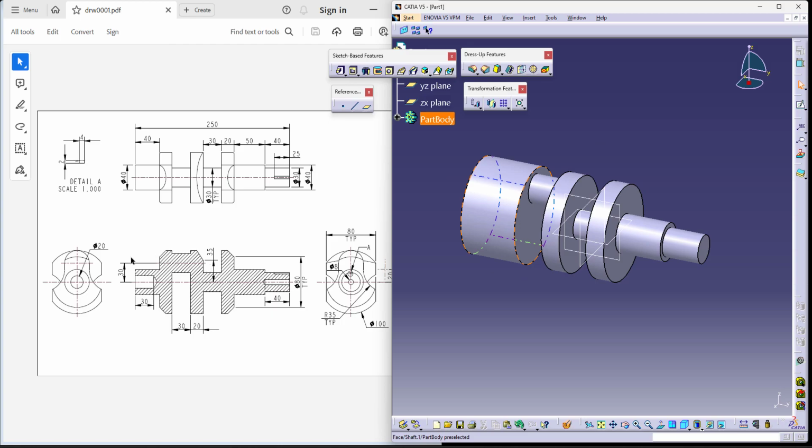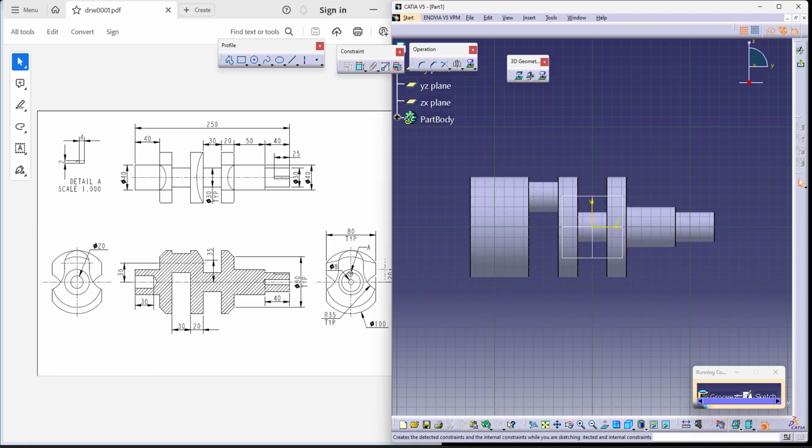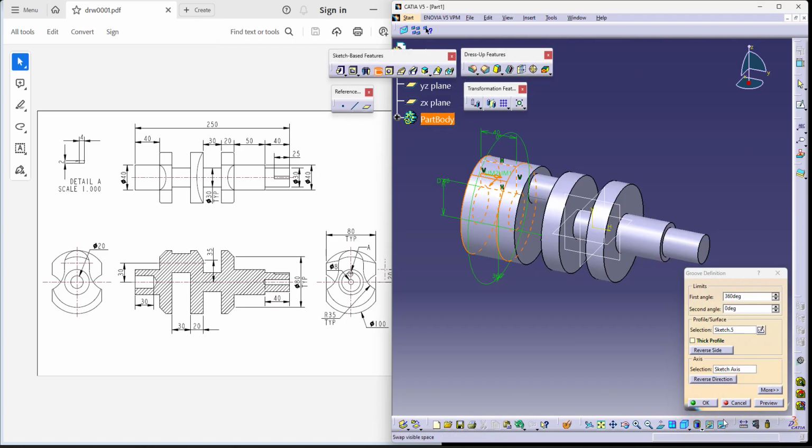Now there's also another cut, 40 by 40. So again, let's try to use the same groove command. This is a very easy cut which we have already done before. But again, let me try to take the references as well as the axes. And I want this reference as well. Now, let me go back to making my profile of which I want to remove and then start dimensioning it. This is supposed to be 40, which I've already mentioned a minute ago. This also is supposed to be 40. Exit, it tries to remove the material.